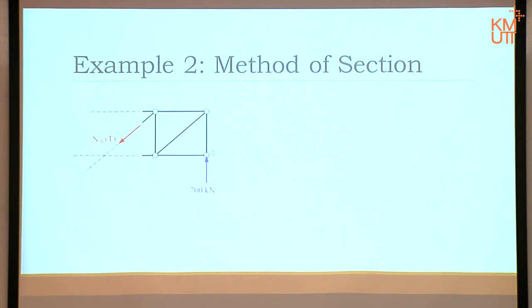Now, let's go for the one below here, NC first, because NC is easier to analyze than NA. If I want to know the NC direction, I have to eliminate the need for NB and NA, right? So I take moment about this point here, which I will call point 3. That's 700 pushing up, causing anti-clockwise rotation. To go against it, NC has to cause clockwise rotation, meaning it has to go to the left hand side. There we are. Right?